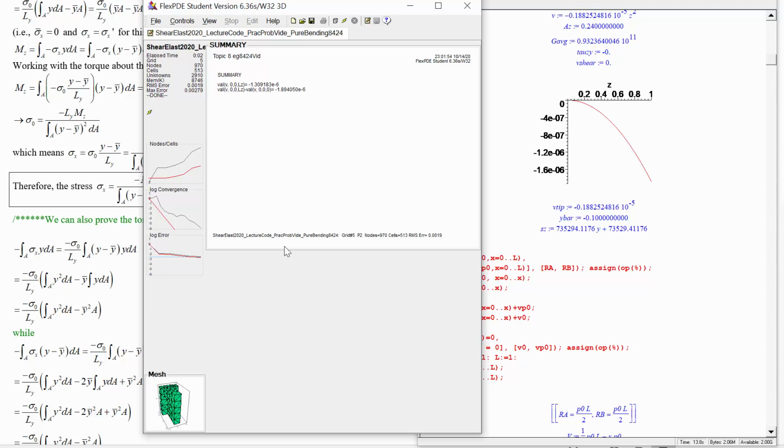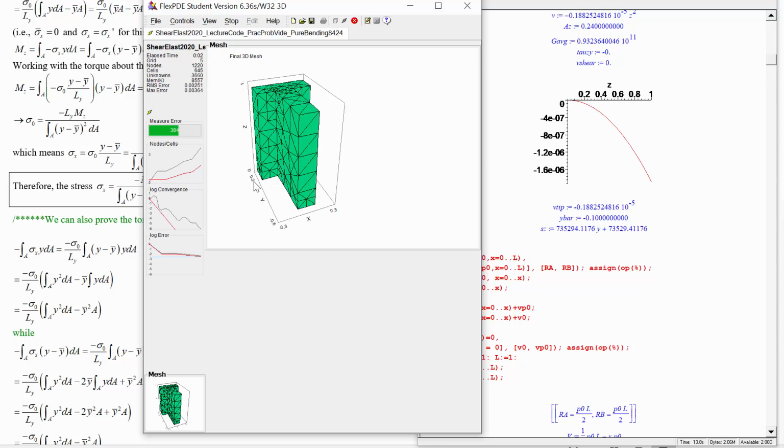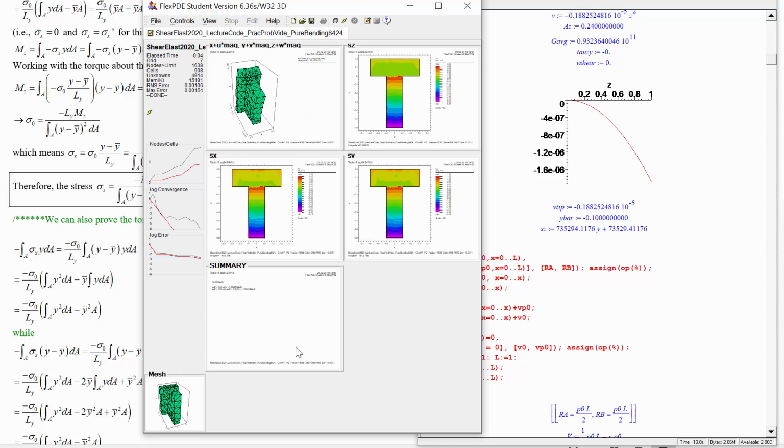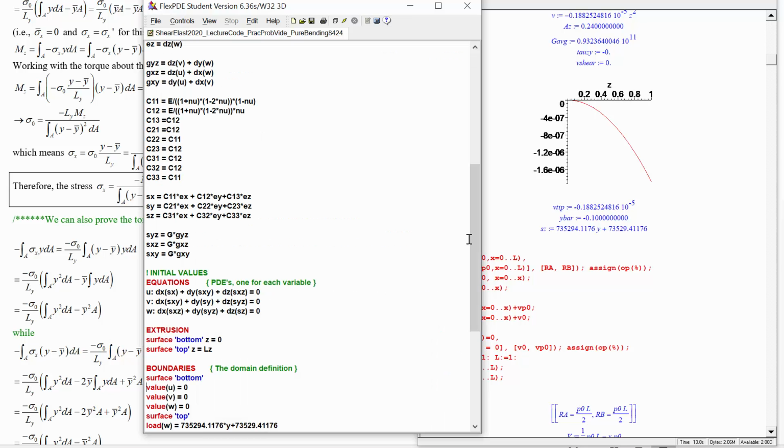All right, well, let's refix that surface and put in those things there, and now we're going to have those two things being exactly the same answer in FlexPDE because there's no displacement at the 0, 0, 0 point because it's on the Z equals 0 surface, and we fixed that now.